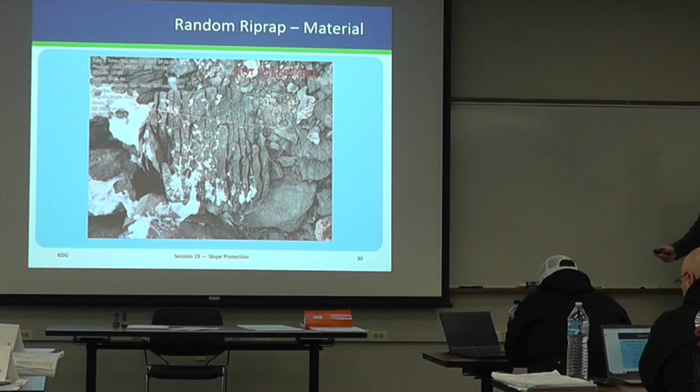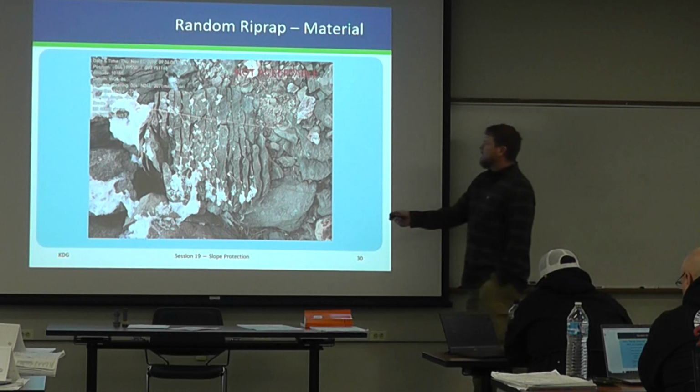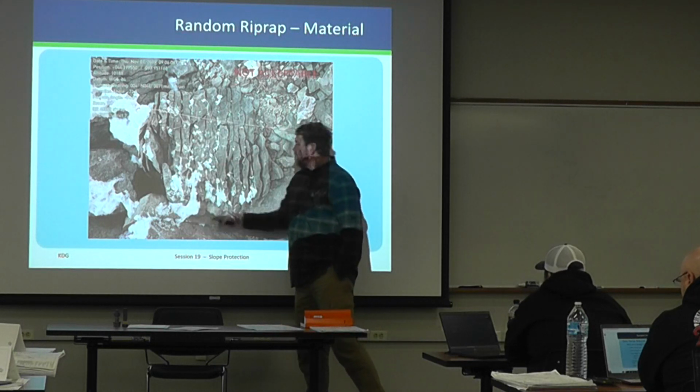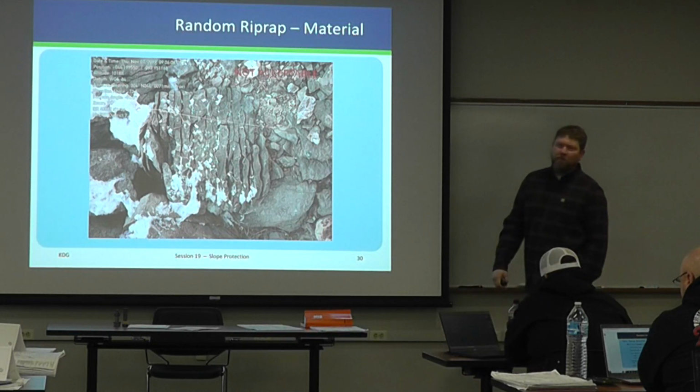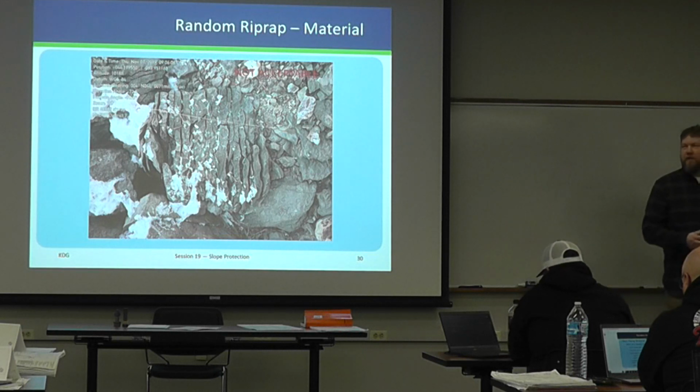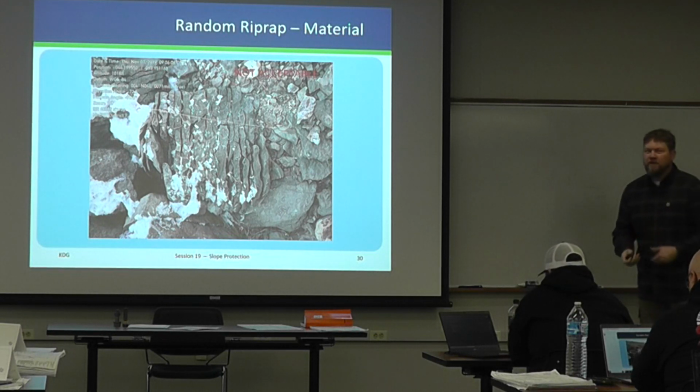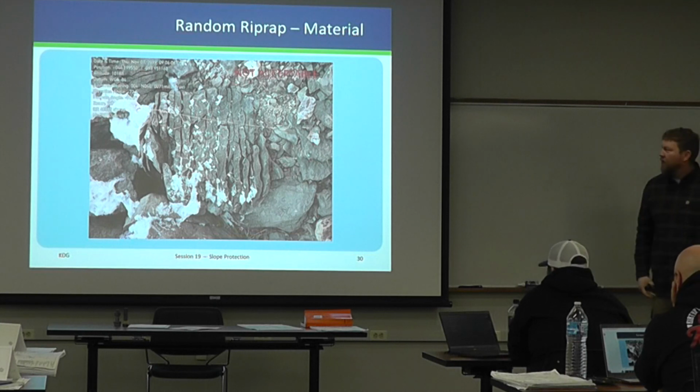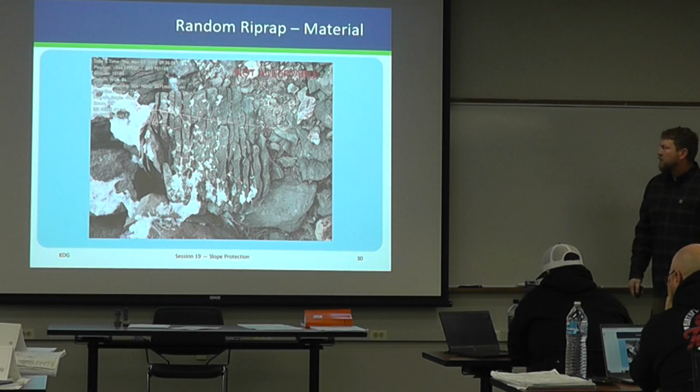What do you think happened on this piece? Freeze-thaw, yep, there's maybe some of that soluble material in there that after a winter of water getting into it, it leached away. So this piece started off being rather large, right? Now we've got 30 small pieces. When you've got a flow coming through at 10 feet per second, do you think that's going to hold as well when it's broken up into a bunch of little slabs? No. So this one's an important one, and this was a District 7 project. Want to be on the watch out for that. It's going to be more of your sedimentary style rock that's going to have this kind of issue.